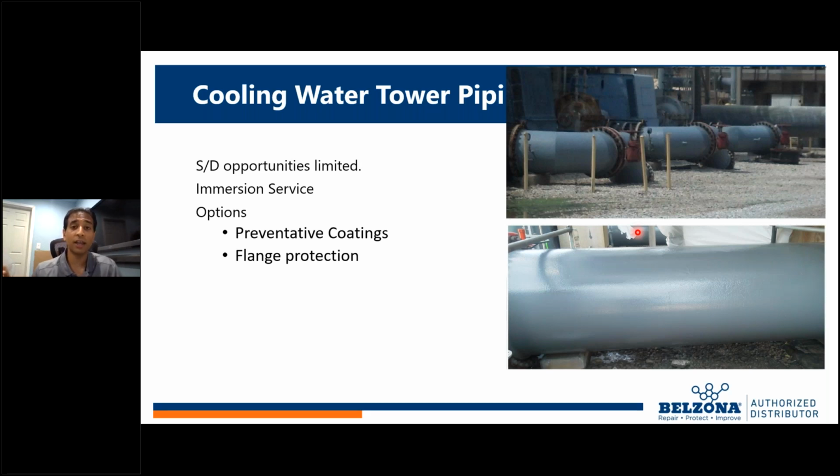Cooling towers generally tie in to a large portion of the plant, not just one single portion of the facility at one time. And so this is a huge Achilles heel that could potentially get you in trouble, and there's a huge LPO associated with it. Yes, it's just water. It springs a leak. What's the big deal? The big deal is that if you can't stop it, you might have to shut down your operations. And you couldn't do something about it. You put in an epoxy coating system, you eliminate the threat.